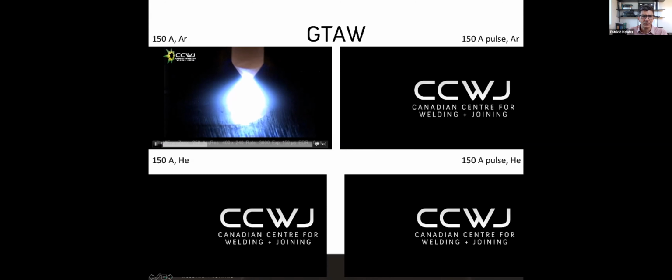So let's start with argon. So this is what a TIG weld looks like. In this case it is automatic welding. So the torch is held by a machine. And this looks like a photo, but in reality it's a video, right? And if you pay attention, you're gonna see how the torch is moving to the right, but we did it at high speed. So it looks like it stopped. This is the argon arc. Here we have the electrode. Down here we have the plate. Right under the arc, we have the weld pool, and this very bright part is the arc.